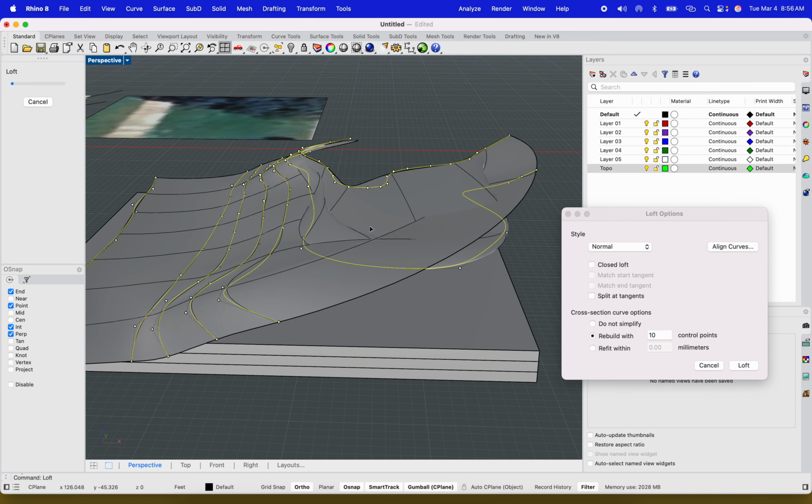And what this tells me is that some lines are flipped. However, keep in mind the way that I trace this. Some lines I started from the top and I traced down. Some lines I started from the bottom and traced up. And that actually causes the direction of the lines to change. So you see how it's kind of like flipping in on itself? Be careful when you run into these errors. That's because some of the lines are technically flipped, right?